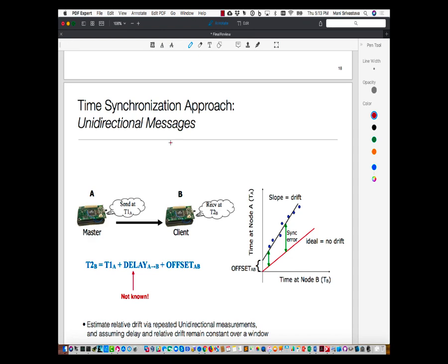Over the course of grading your assignment, there's not going to be much of a clock drift, right? So if you think about it, there are two factors at play. One is your clock drifts, and the other is that this basic equation has errors when we actually implement it because of all these quantization and other uncontrollable delays. So you should do it multiple times to get an averaging, right?